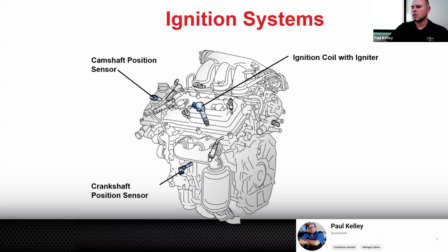And I was kind of like, did you see any other tools besides the scan tool? And she's like, well, he had the diagnostic machine. And I was like, yeah, I think I'm going to take that as a no, right? So it sounds to me that the mobile mechanic showed up, checked codes, saw that it had a misfire on a certain cylinder, replaced that coil, and she requested he did an oil change. Anybody want to take a guess at that bill?